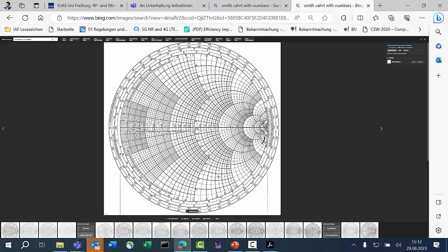These branches then are this impedance, and when you are 50 ohms, you are on this circle. This circle is all the impedances which have 50 ohms as a real part. And if it's 10 ohms, it would be, for example, here. There would be an annotation: this would be 1 times I 50 ohms, or 2 times I 50 ohms, or 3 times and 4 times.